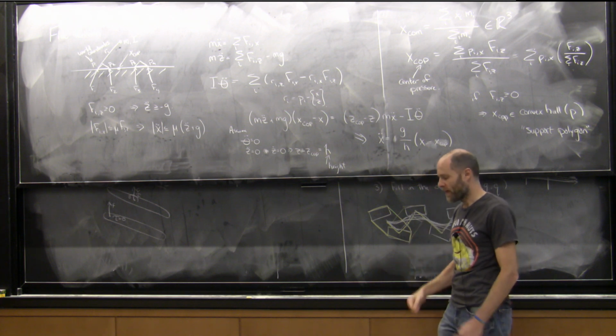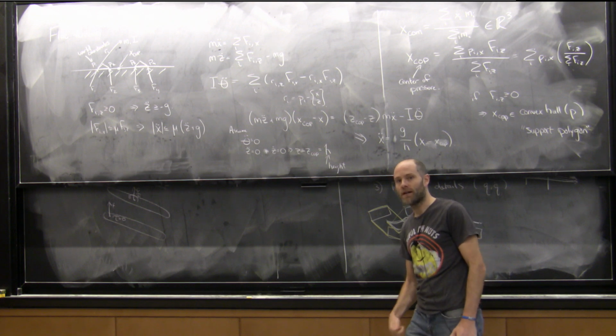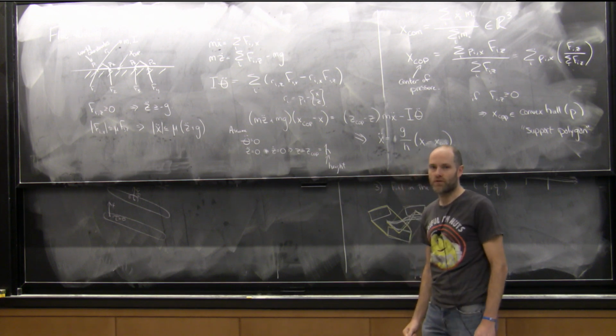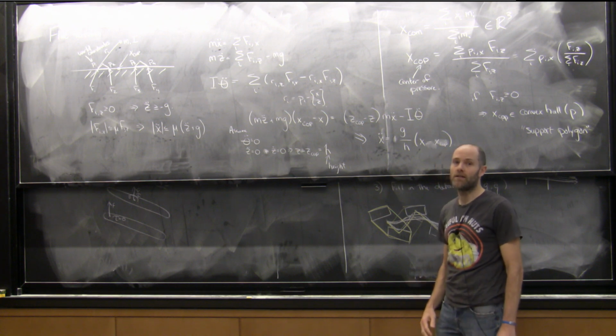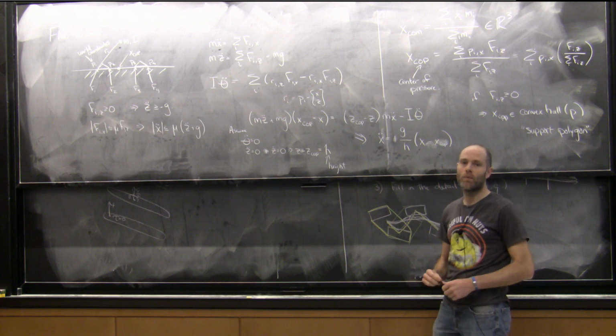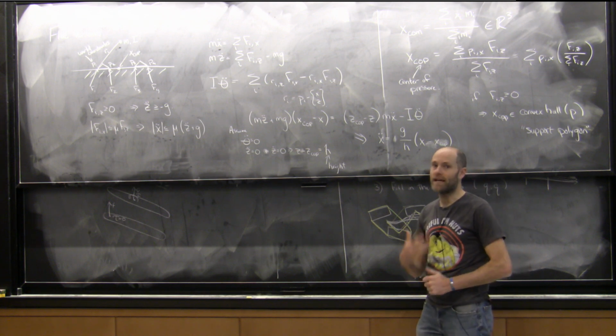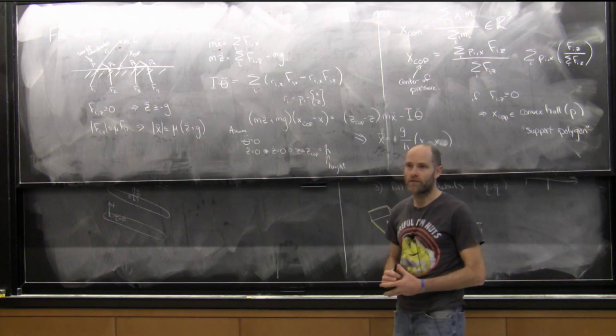Then if I just move through the kinematic trajectory to make my center of mass do the right thing, I am controlling my ground reaction forces. That's the big idea. That's why these highly geared harmonic drive actuated robots are able to do really dynamic things. You control your center of mass, you control your ground reaction forces.